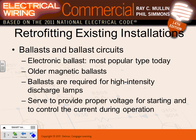Okay, ballast and ballast circuit. Now, arc fixtures need a ballast. The ballast has two jobs. Kerry, my friend, if anybody asks you, job number one, pulls the voltage up high enough to start the arc. And when the arc is started, if you don't reduce the current, the circuit breaker will trip and think you have an arc fault or a short circuit. Then it will choke the current, reduce it to an acceptable level to maintain the arc without tripping the circuit breaker. That's really what for the most part it does.